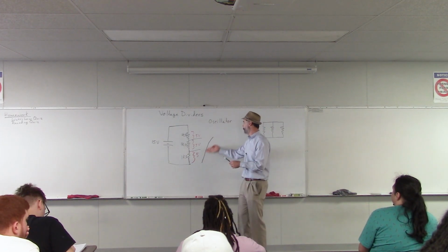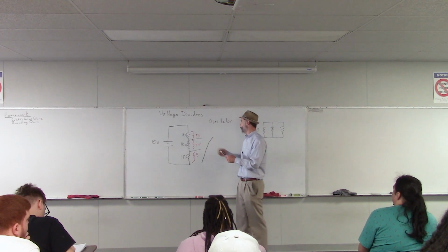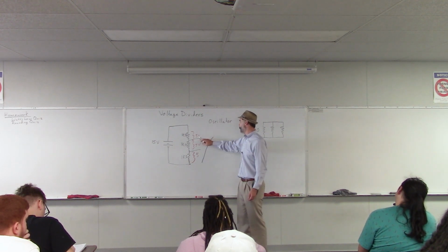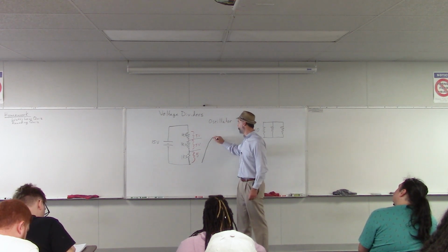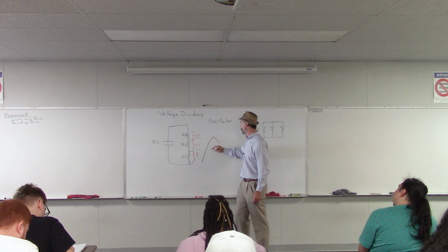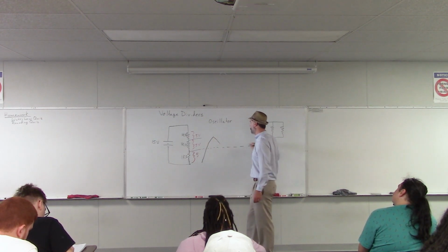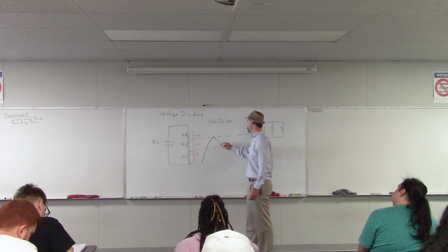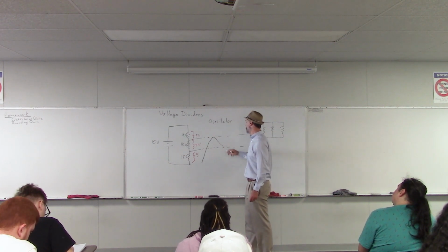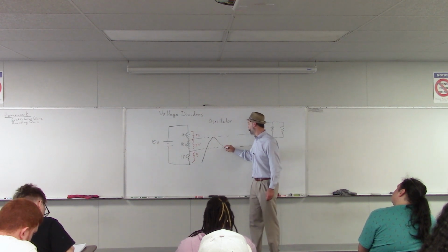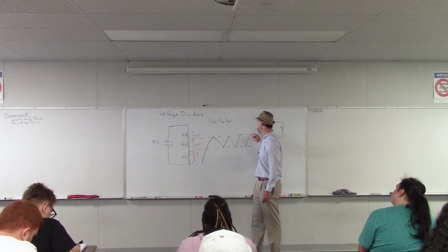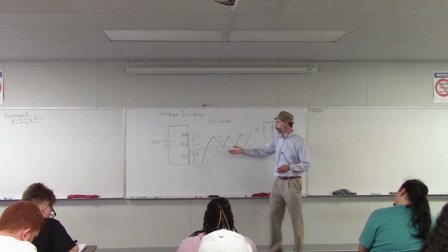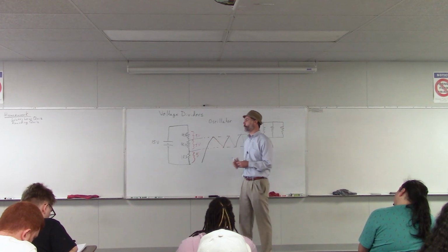And so the circuit has a little device called a comparator that compares two voltages. It compares this charging voltage with this reference voltage, and when the charging voltage reaches the reference voltage, the circuit flips a switch and starts discharging. Now this voltage goes down and down until it gets to this lower reference down here. Then the circuit flips another switch and it starts charging up again. So it keeps going back and forth between these two reference voltages. We're not drawing power from this circuit, but we're using those voltages as references.